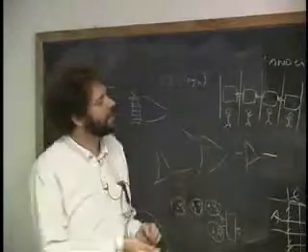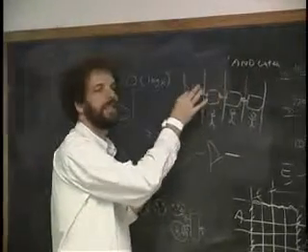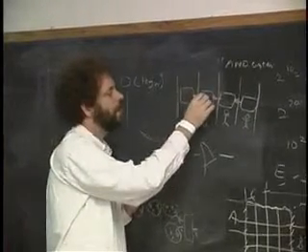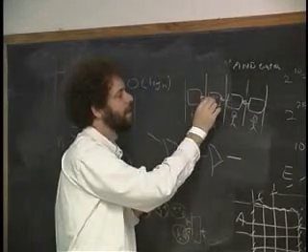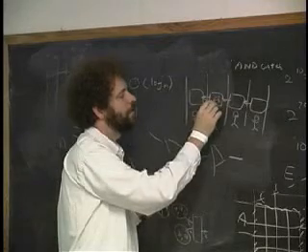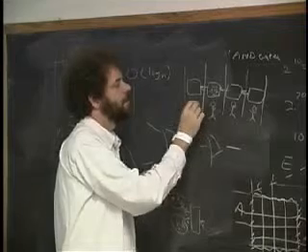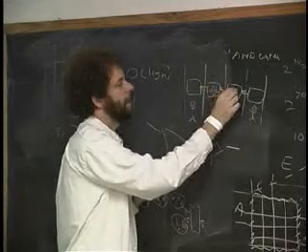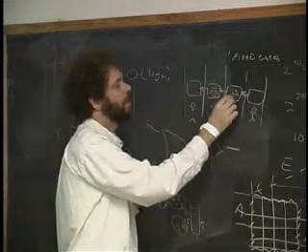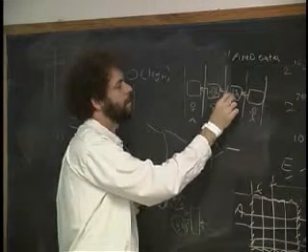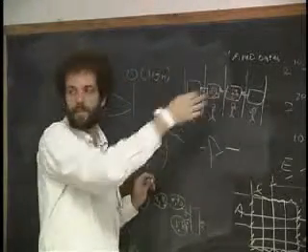And the idea here is that the add for a given number proceeds through the line in stages. And while one add is having bit number 20 done, so here's add, A plus B, and it's the add number K, the next one is having bit number 19 done, and that's A plus B, but it's a different A and a different B, and it's number L. Okay, and so each one of them is going to march through. And so we will pipeline.